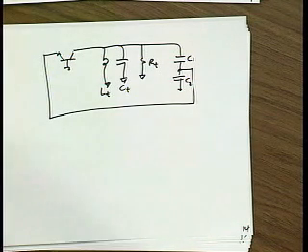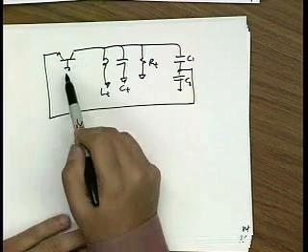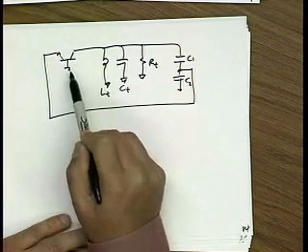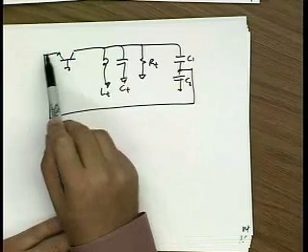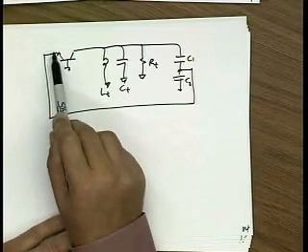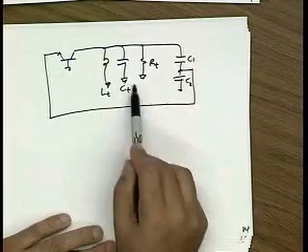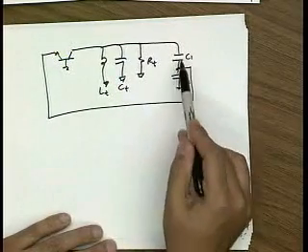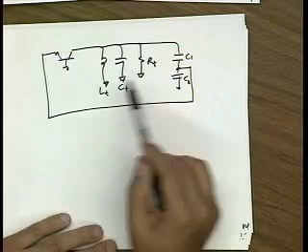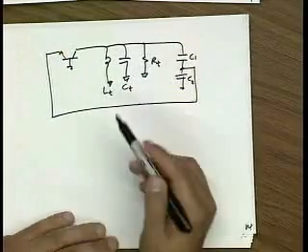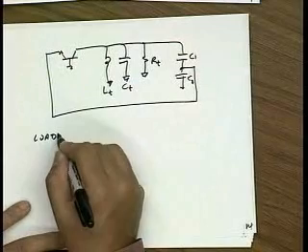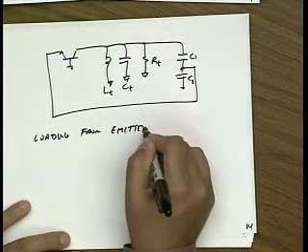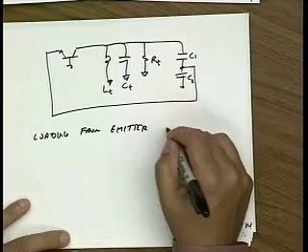That's right, yeah. So remember, in the common emitter oscillator, we're looking into the base, which is a high impedance. Now we're looking into the emitter, which is a low impedance. And that transformed loads our tank. So that means that I have to make my N ratio pretty big to avoid the loading. So now the loading from the emitter loads the tank.